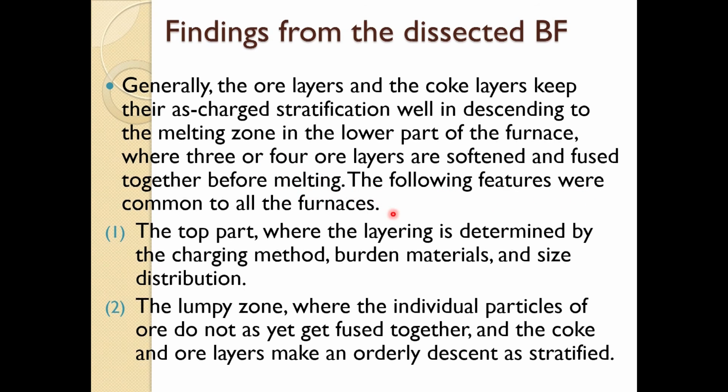And the other important feature, the top part where the layering is determined by charging method, burden material and size distribution. The lumpy zone, where the individual particles of ore do not get fused together, and the coke and ore layers make an orderly descent as stratified. So, as long as they are not fused and temperature is not very high, in a very orderly manner they descend into the lower portion.